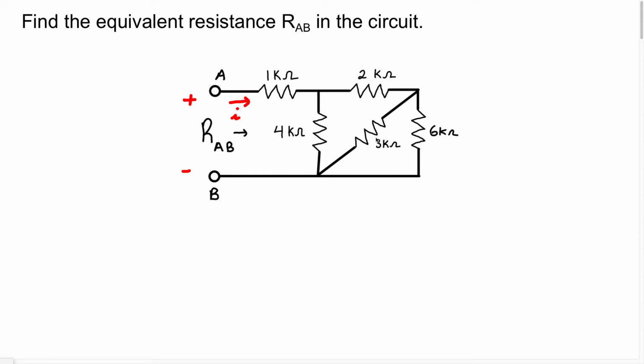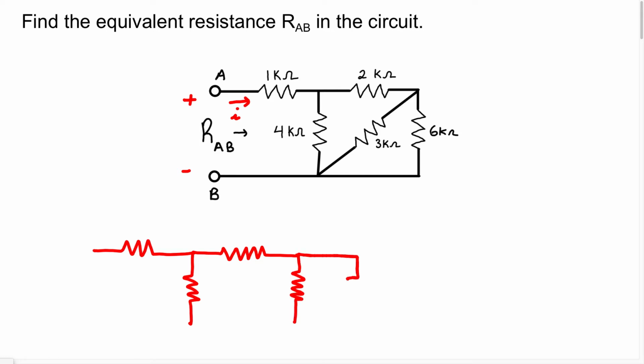Are these resistors in series or parallel? That's a good question. Well, let's just redraw this and then we'll talk about it some more. I'm just going to redraw it really quickly. Once we get here, with this slanted wire, I'm actually just going to draw it as a vertical wire. And because there are no resistors at the bottom, I can just draw the wire at the bottom.